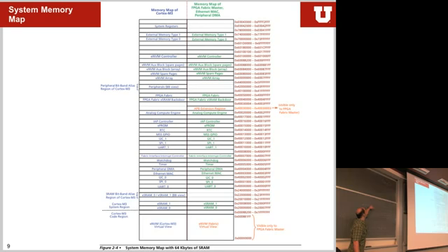And the status register would be, if you want to read the status of this register, you could read it out. So oftentimes, what then happens is that this register would be a read-only register, and these would be write-only registers. If you read from these registers, you get garbage back most of the time, or just zeros. But there's no meaning behind them. So that's a different way of how they oftentimes make access to registers available without having to go and read the whole status out. The other one is using the bitband area, where you can address individual bits of certain memory locations.